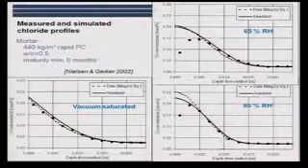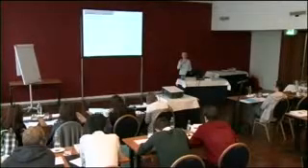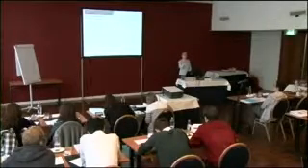And it seems for this concrete to work quite well. What you should consider is that we have a fairly high water cement ratio. That means that we have an interconnected capillary porosity. If the capillary porosity is not interconnected, you can't use this. But in that way, we could actually explain the difference between what we observed in situ and what we observed in the lab.